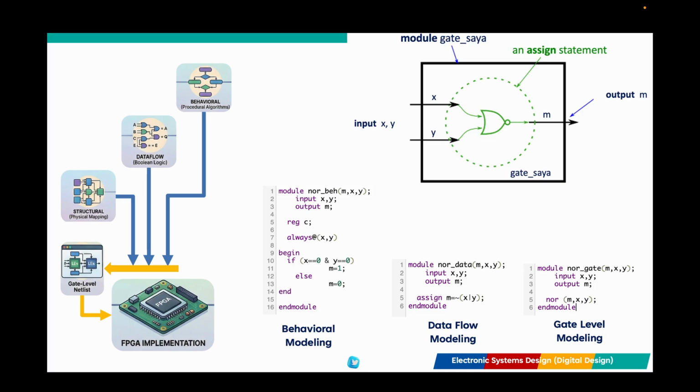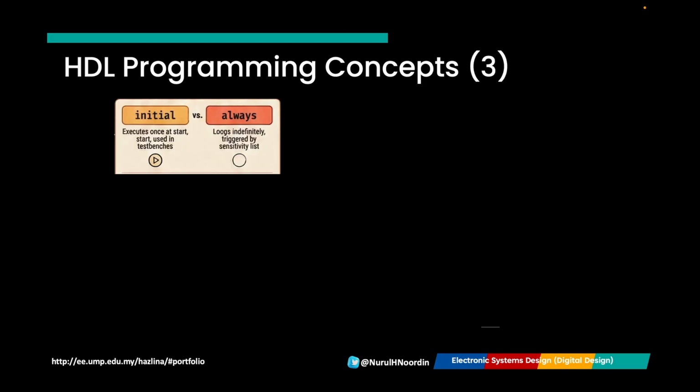It allows you to design at the speed of thought while letting the synthesis tool handle the heavy lifting of physical implementation. Now let's move into the procedural blocks in Verilog. Hardware operates concurrently, but within Verilog, you can write procedural statements executed in sequence. These must be encapsulated in specific blocks, such as shown here.